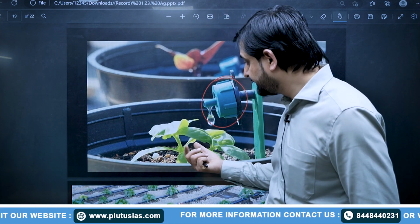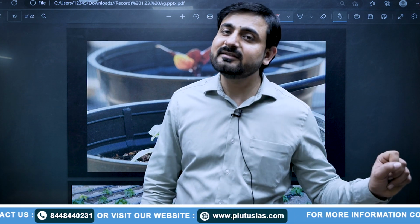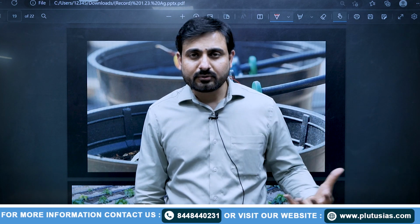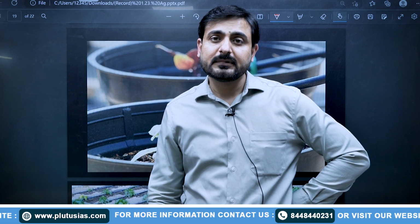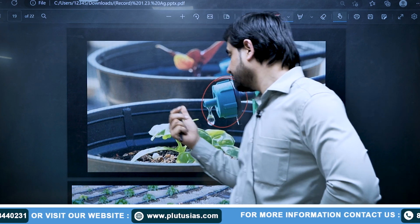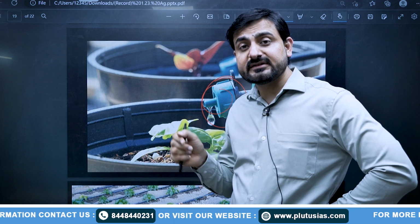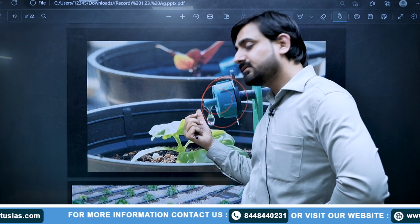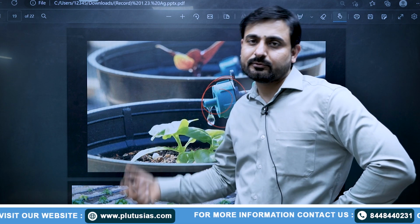Then what are the reasons that farmers are not adopting drip irrigation at a large scale? This is because it causes more cost because of all such pipes, nozzles, etc. It requires more skilled labor. Again, maintenance cost. Also, you require clean water, otherwise these nozzles can be choked. Further, it increases salt concentration around the root of the plants, and it is only used in limited areas. Okay, not at every place is it suitable.